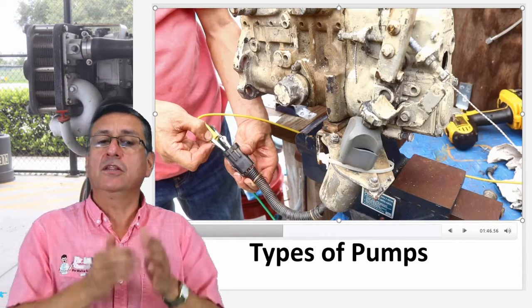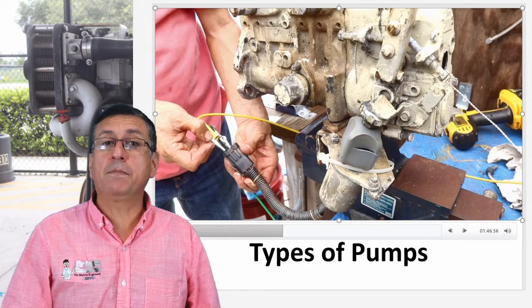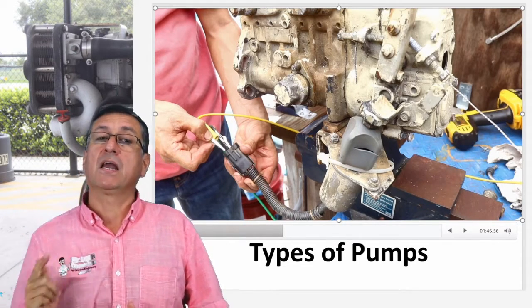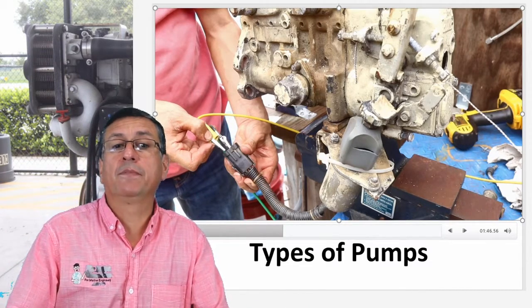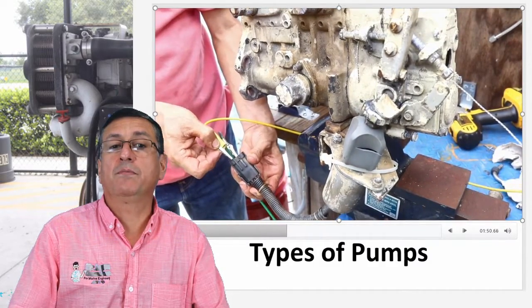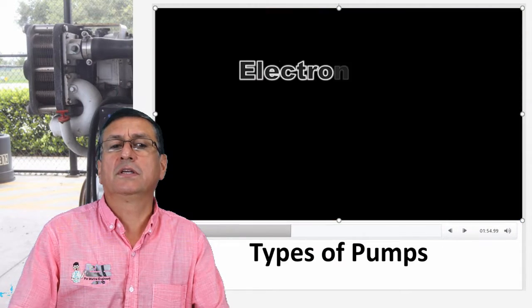Right? In the majority of diesel engines, they stop because the solenoid at the input of the fuel injection pump cuts the input of fuel to the pump. All right? This is the solenoid. All right? To activate the pump, perfect. To start and stop.